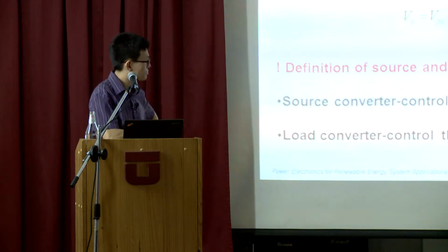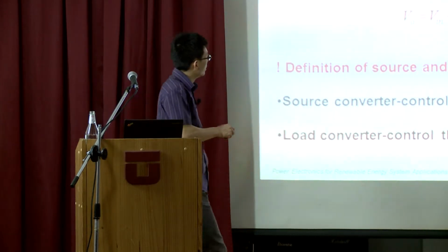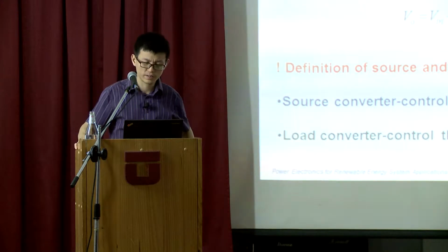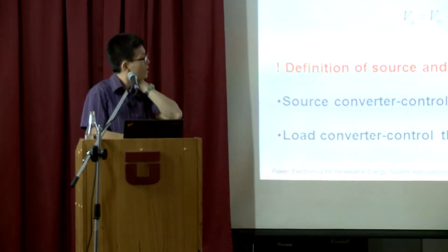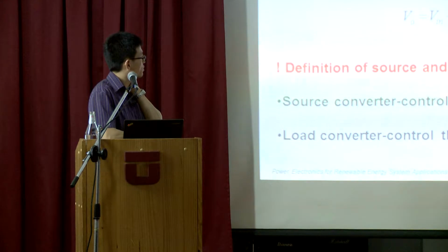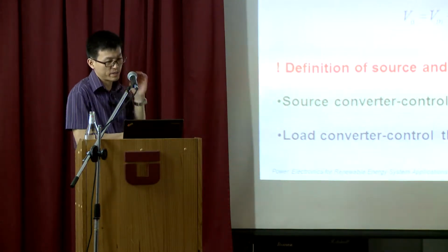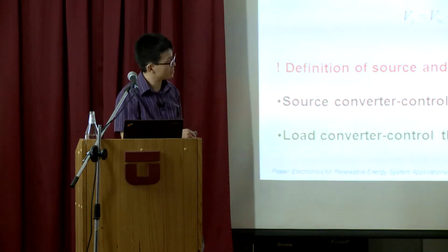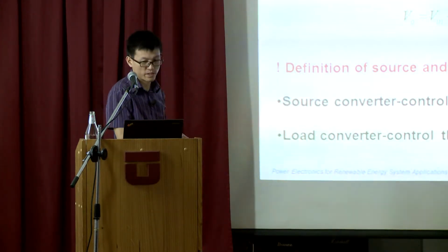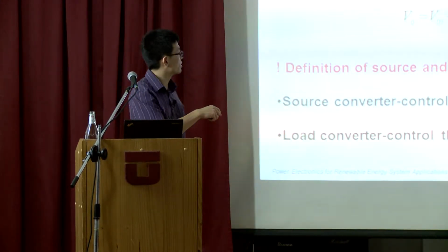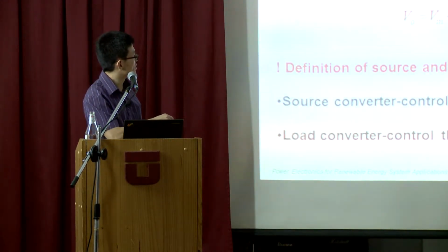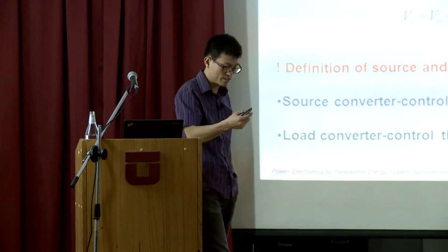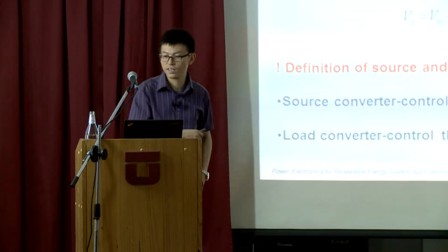The voltage on the load side is essentially like a resistive series circuit. You have the output impedance of the source and the input impedance of the load connected in series, and you calculate the voltage. This is very much like resistive circuits in series. We learn this in the first year.